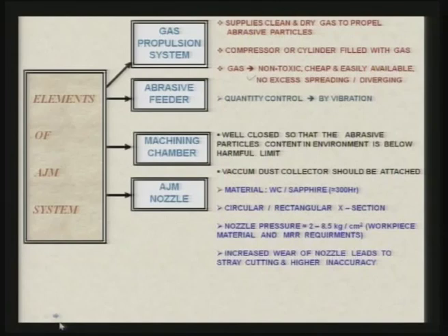Now, increased wear of the nozzle leads to stray cutting and higher inaccuracy. We should use the material of the nozzle such that the wear of the nozzle is minimal. If there is excess wear of the nozzle, then definitely you are not going to get an accurate workpiece over there, as I can just show you over here.